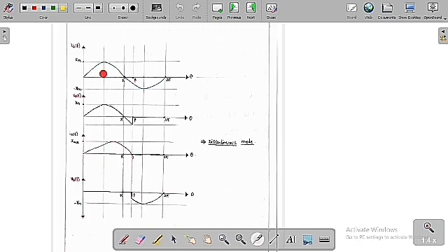As the source voltage is a pure sinusoidal waveform, we are going to get it in this format from 0 to pi and pi to 2 pi, with peak values of plus Vm and minus Vm. Now the output voltage: in the previous case, from 0 to 2 pi, the diode was conducting. So now the diode will conduct only in a part of the range.